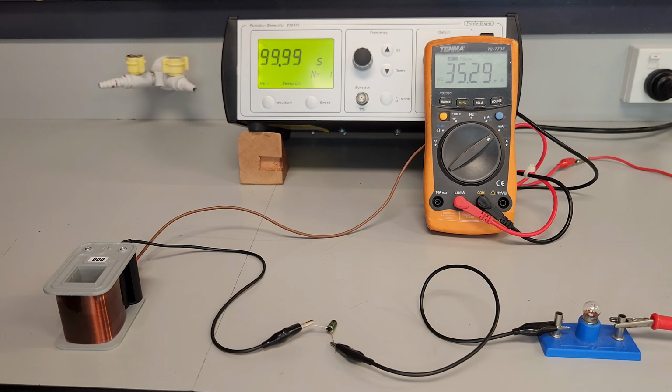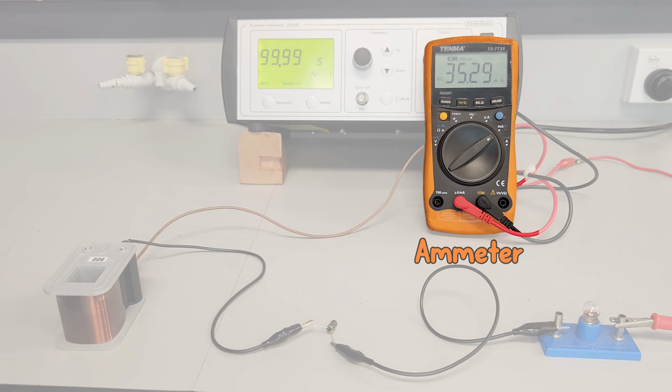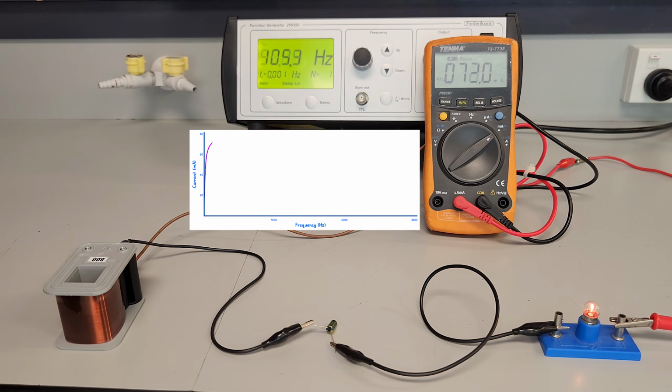I have here a series LCR circuit with an inductor, capacitor, and resistor for which I'm using a lamp. I also have an ammeter displaying the current. Sweeping the frequency of the AC supply from low to high, we see the current peak at around 222 Hz.